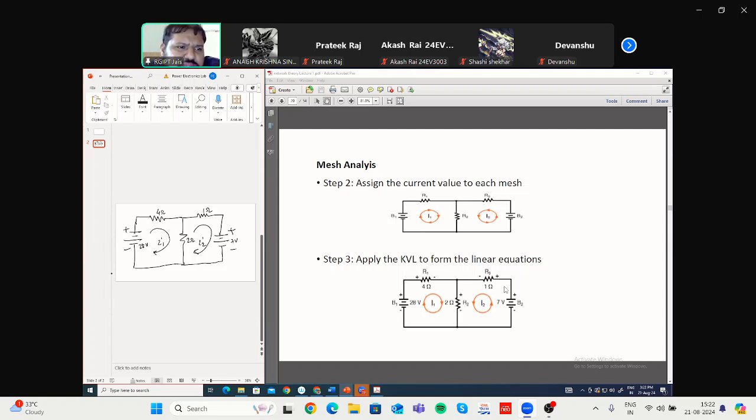But what about this resistance? In resistance, the current flows, there is a voltage drop. That means it is absorbing energy. Whatever energy the supplier, the battery, supplies, the resistance always absorbs. For inductor and capacitor it is a bit different, it depends on the cycle, but for resistance it always absorbs energy. So if it's absorbing energy, it is working in opposition to the energy supplier. If the energy supplier is in a particular direction, the energy absorbed by the resistances should be in the opposite direction.